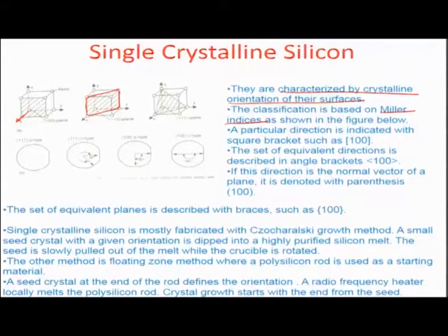So, that is how the 110 direction is represented. When we talk about directions in such an orthogonal coordinate system, the Miller indices always show the indicated direction and the indicated plane across which the perpendicular to that plane would be the indicated direction.